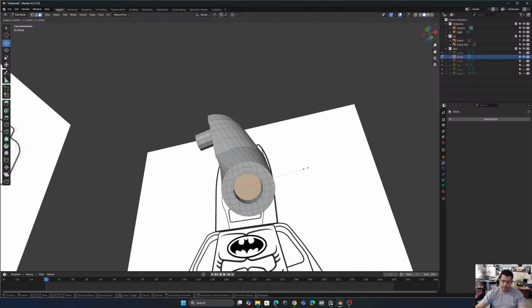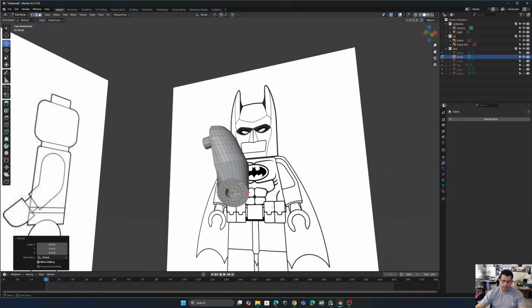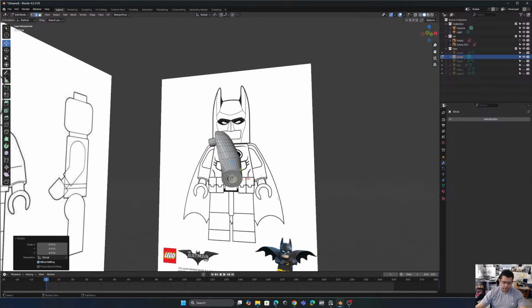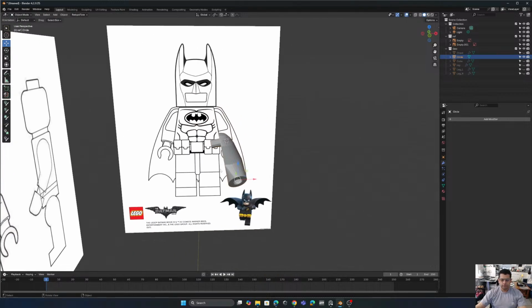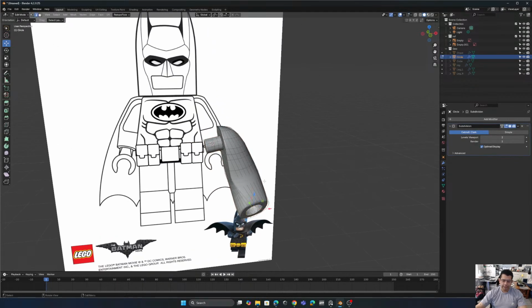We're gonna scale that face a little bit, and after that, pressing 2 on the top numbers, we're gonna go to edge mode, select this edge, and we're gonna scale it too to have a smaller hole. I think that's gonna be perfect. Now Tab to go out of edit mode. Control 2 to smooth it a little bit.